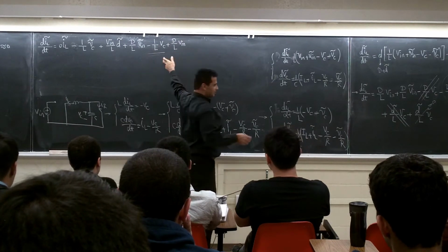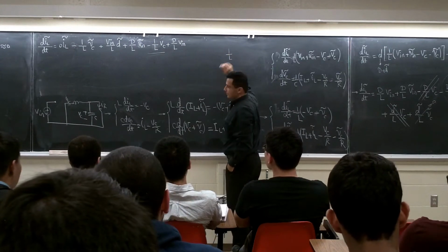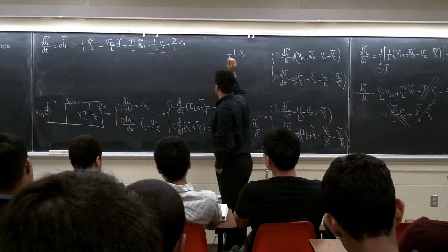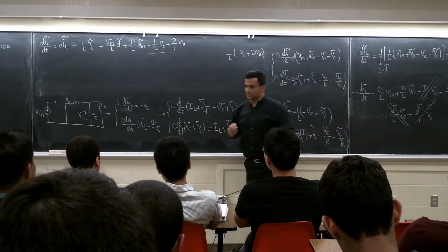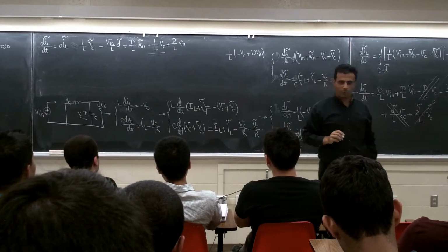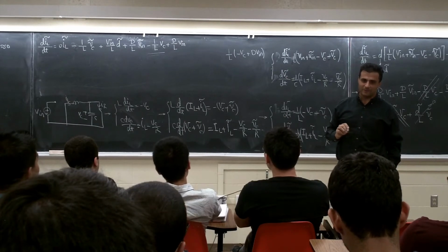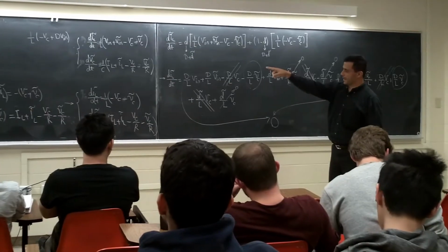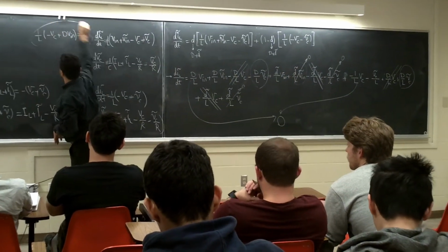Okay. There is one more thing. Look at this term. I'm going to take a factor 1 over L, right? It's going to be minus Vc, I'm writing these two terms, right? Plus D Vin. How much is this term? 0. Why? Because of the converter. Vc is Vo, that's a buck converter, right? You can write that equation here. This one is going to be 0, right?